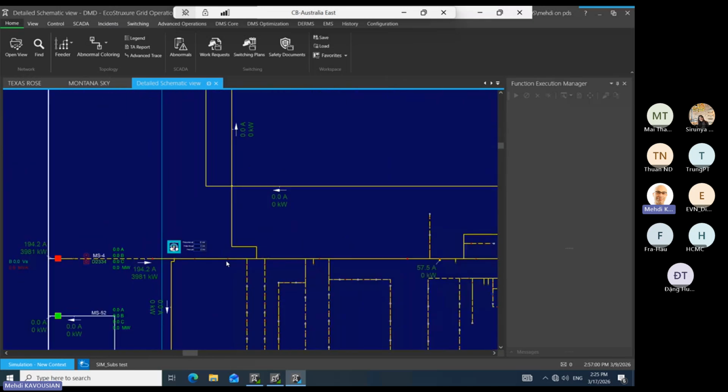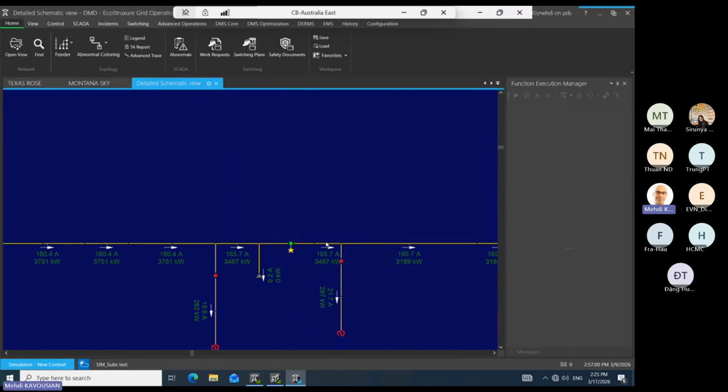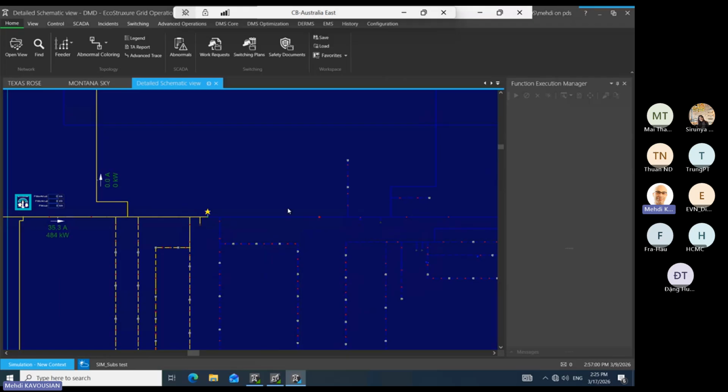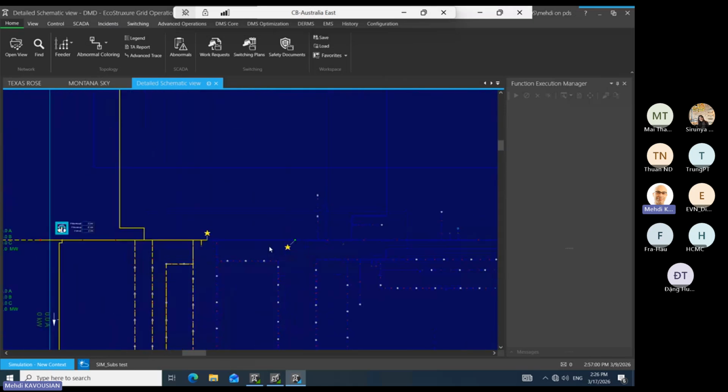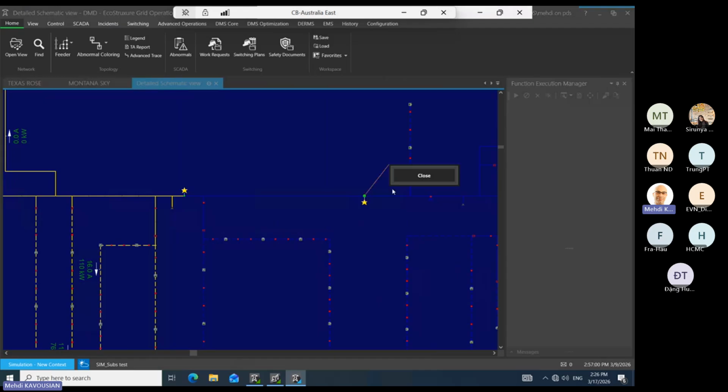And then I want to, let's say this is a fault. I'm saying this is a fault here. So I have to isolate them. When I open here, it's not actually impacting the real time. It's just a study. So I have work to do here probably. So yeah, I open these two switches. Okay, so this becomes de-energized. And before doing this, let's observe some of the results already. So just sorry before that.